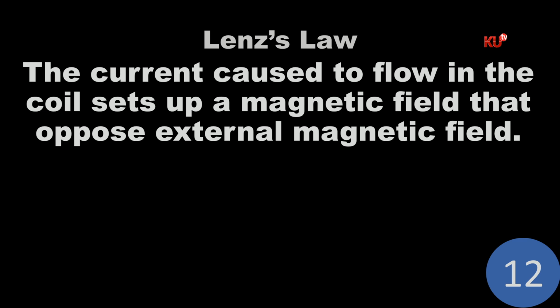And so when current flows clockwise, we use the clock rule to predict the polarity of this face. So if one views the end of the coil and current flows in the clockwise direction, that end is the south. Otherwise, if anticlockwise, it is the north.